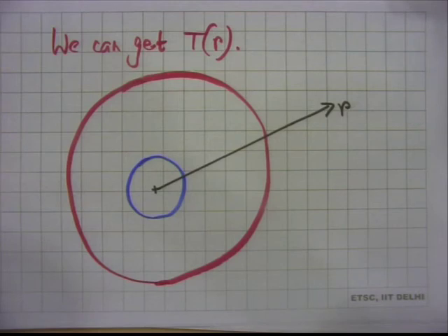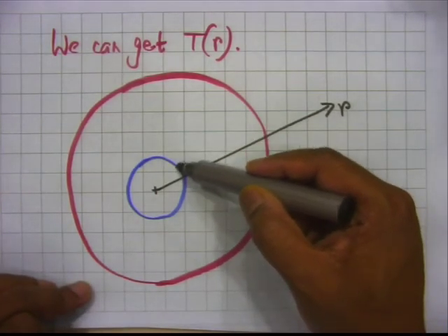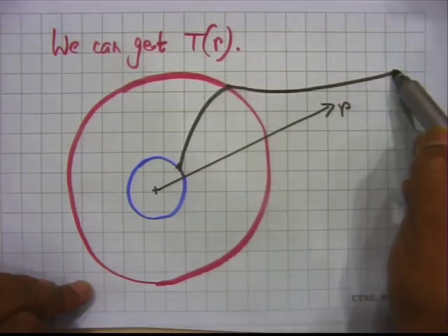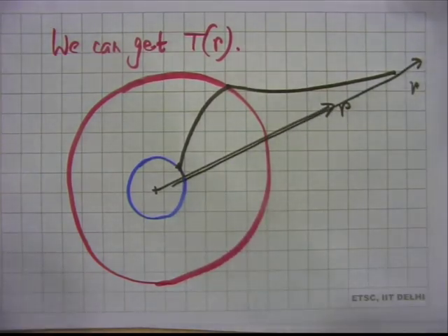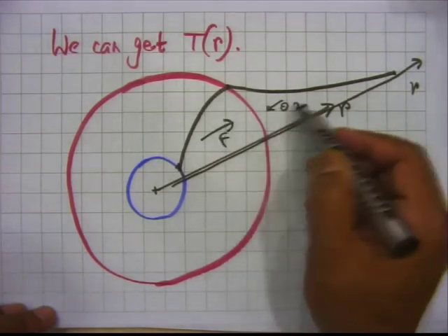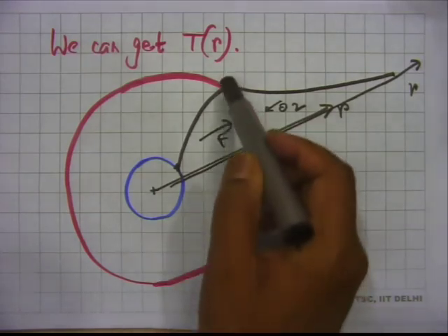Okay. So, here there is some temperature and then the temperature has to go up in this region, and then the temperature will drop down if we show it as a function of the radial distance. That is what we expect, because at the flame the temperature will be higher, and we already have some diffusion flame background. So, we know that there is fuel going this way and oxidizer coming this way, they will meet here and they will react. They will produce the maximum temperature where they meet and react.